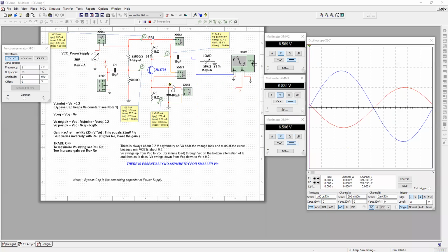Now let's move into the circuit towards the amplifier and the output. We could have decided to increase the resistance here because all we needed to do was create a greater separation between the two impedances. And so that meant we could have increased the resistor value also. However, remember that this is a voltage divider, and that means that we're assuming no current is flowing into this transistor's base, or that's the ideal assumption, but we will say virtually, practically no current is going into the base.